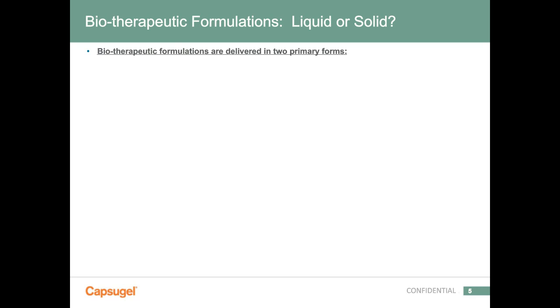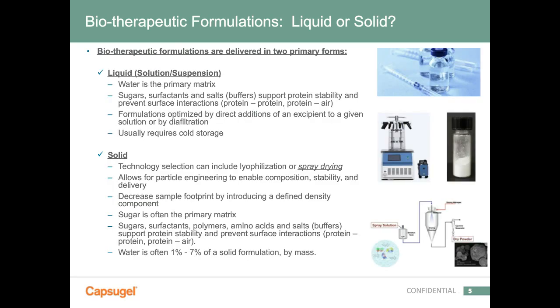Now the solid form is the second way of doing biotherapeutic formulations. The technology is usually focused on either lyophilization or, in this case, spray drying, which we'll talk about during today's webinar. Conversion to the solid form is usually used as an alternative when liquid-based formulations have complications or specific needs. And lyophilization is considered the gold standard.